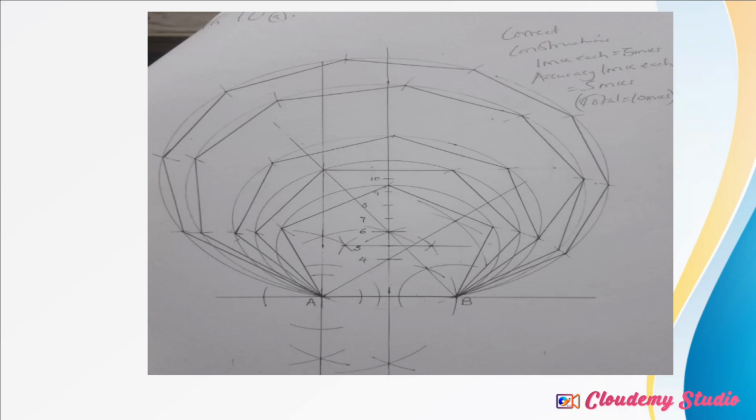Then at point A, you construct an angle of 45 degrees, and at point B, you construct an angle of 60 degrees. Whichever the case, you can start at point A with 45 and point B with 60, or the other way around. I started by constructing the 45 degree angle at point A. And I said that for you to construct an angle of 45 degrees, first you have to construct an angle of 90, then you bisect the 90 degree angle to get 45 degrees. That's exactly what I did, if you can see from the diagram.